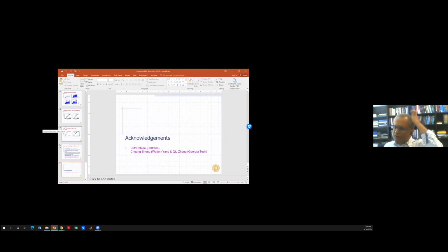Yes, so collapse is an extremely difficult state to capture, and the way we defined it here was a 50% loss in the lateral strength. In some cases we just didn't achieve that. We simply had so many bars rupture that at the end we decided that damage state 6 was sometimes the same as damage state 7. For example, in the full-scale test done at San Diego, the column really didn't collapse.